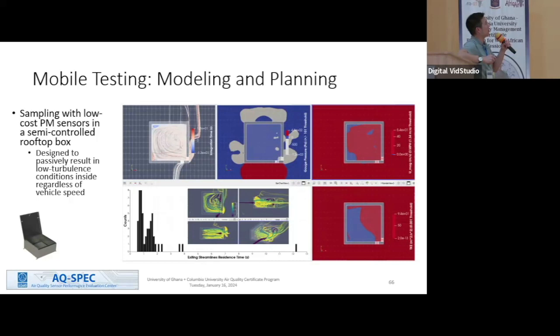And then when you do the CFD model, you can actually see that the gas streamlines are making this kind of circuitous pathway before they exit out the outlet. And so that's kind of nice because it lets you have a well-mixed box for your sensors to sample from. It allows some amount of residence time in there. And also, if you put sensors around here, it's not that turbulent. So that's also a nice, peaceful, calm location for the sensors.